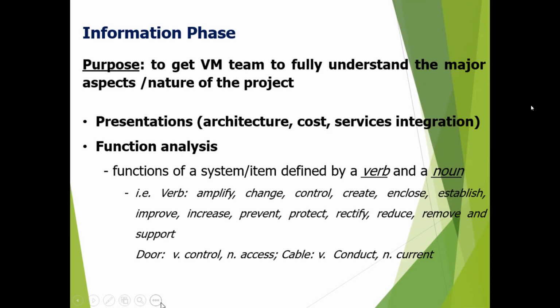So each and every function is identified and studied carefully, by asking the question, why is this there? If there is a door, you see whether this door is required, whether it can be replaced or removed. By removing it, you're going to have some cost saving, and obviously construction time will be saved. But what happens to the functional performance if the door is removed?